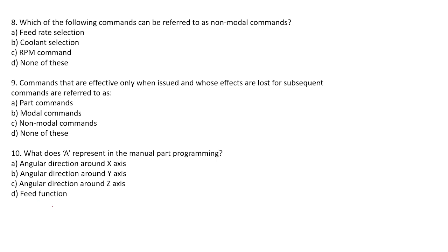Commands that are effective only when used, and whose effects are lost for subsequent commands, are referred to as non-modal commands. Whatever I have said in that example, say you want to apply a command to some small segment of that program, you will use that particular command. So that command we can call a non-modal command.